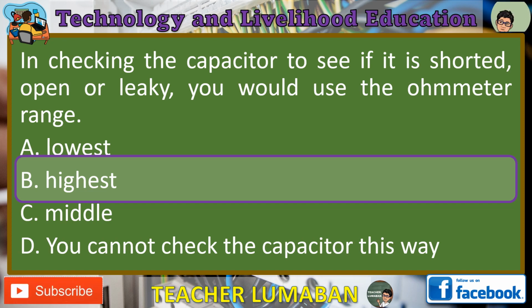Ensure safety. Before proceeding, make sure the capacitor is discharged to avoid any electrical shock. If it was recently in use, wait for a few minutes to allow the charge to dissipate or use a discharge tool.